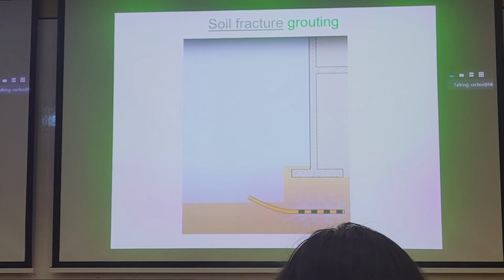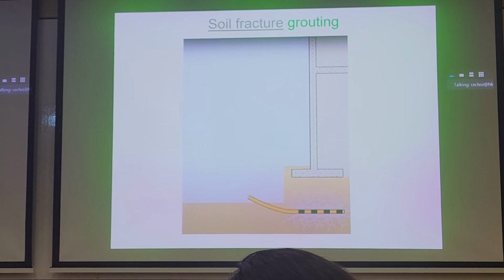But the point that soil fracture grouting is good for compensation is because it's not like one massive ball of grout that's uncontrolled, right? You can slowly form cracks and fissures, and the combination of these veins in the ground can slowly increase the stress in the ground, rather than one big injection displacement of the ground with a very dense piece of grout.